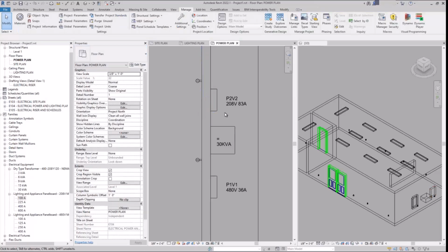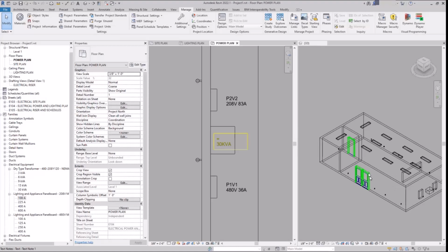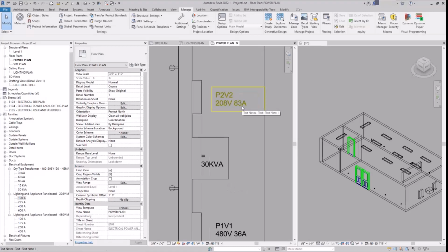When you specify 100% rated breaker, they are much more expensive, much longer lead time. They have their place, and they're really awesome. And I've used them on multiple occasions. But when it's a cabin in the middle of nowhere, there's not really a good reason to put a 100% rated breaker in here. So that's why we use 80% breaker and say, hey, look, we need to increase our capacity by 80%, as it were. So that would be how we would do that: 83 amps times 1.25. So at least 104 amps that we need. So that's why we would have gone with 125 amp panel board.